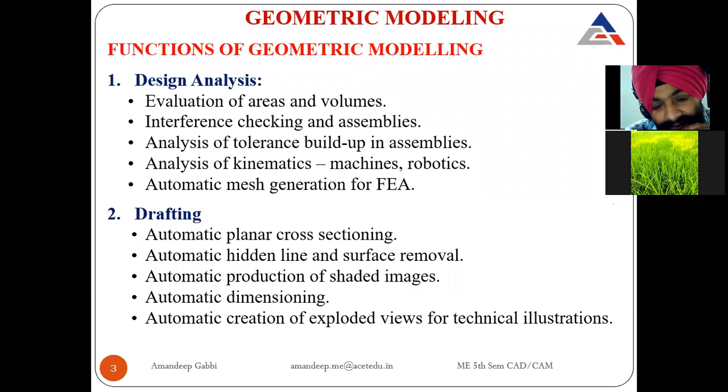Then you want to check the stress analysis. How that is done is with the help of FEA, finite element analysis. On that particular product on which you want to check the stresses, you apply FEA. FEA is dividing that whole surface into a minute number of small areas. Then you check stresses on each small area. This is called FEA. Now, mesh generation is dividing that area into very small parts. We will be doing that chapter, FEA. We will get more clear when we reach there.